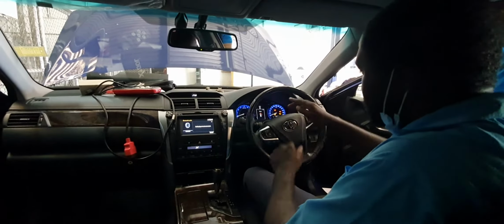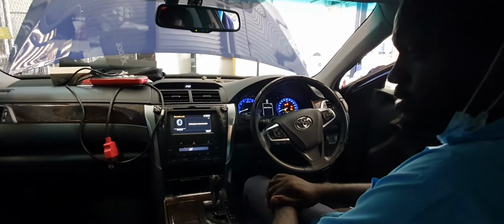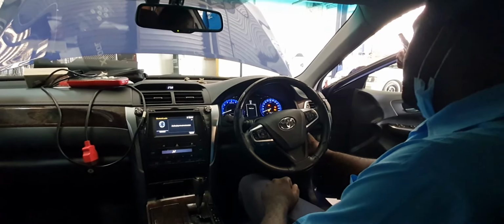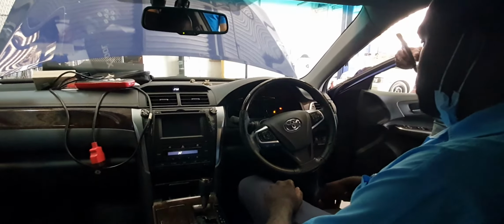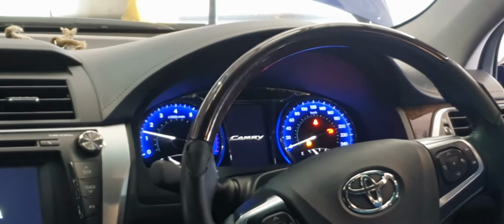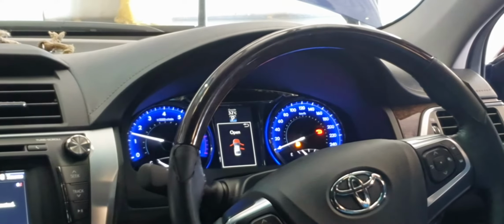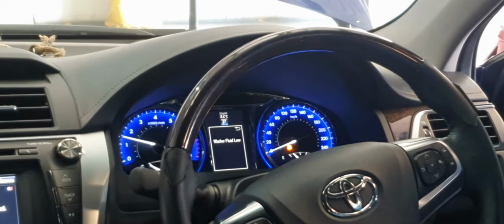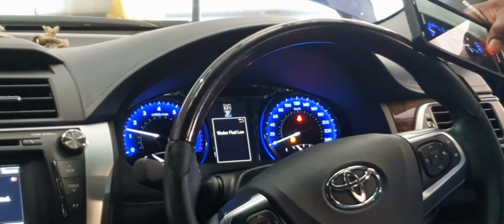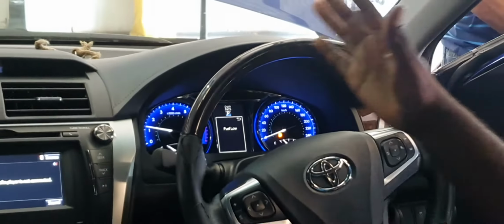But what we're focusing on now is the engine management, or better yet, the powertrain management system. That's why we get the P code. Alright, so if we start this vehicle, all of these lights are supposed to go out. The fuel light is still on because the fuel is low. The engine check light is gone, that means it is working. If I release the handbrake, aka foot brake, it is gone. And if I put on my seat belt, that light is out too. So this is showing that the system is working properly.